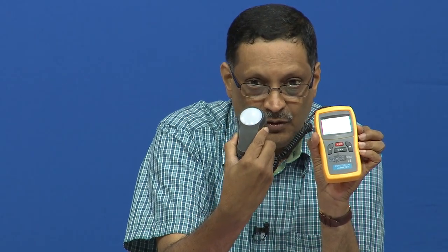That is what I was saying. If you do this, you get 1000, and if you do this, you are down to 200. Even indoors you have this problem. So unless you orient your panels properly indoors, you are not likely to harvest in an efficient manner. Therefore the big takeaway is that these panels are fine, but you have to orient them so that you can extract maximum power and energy from this system.